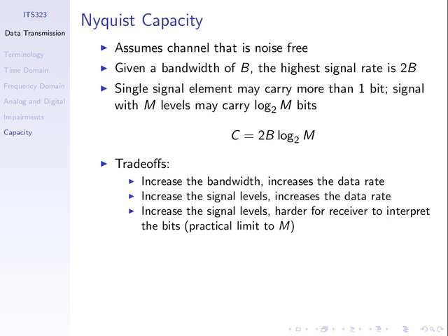If we introduce some random noise, the received signal is different from what is transmitted. If our received signal is now the red signal, the receiver takes a measurement, say it measures in the middle of the period. If it's, say, -5.6, the receiver compares: what is it closer to, -5 or +5?